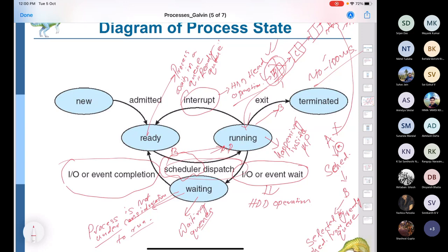So it will give a time interval delta of 1 millisecond for the process to run, and your microprocessor clock frequency is say 1 gigahertz. So in that case, it initializes the down counter with, so basically, this is like 10 to the power 6 clock cycles. It initializes the down counter with 10 to the power 6, and the down counter starts counting down. When it reaches 0, it sends an electrical signal to special pins of the microprocessor telling that the time quantum that was allocated for the process that is running now is over.